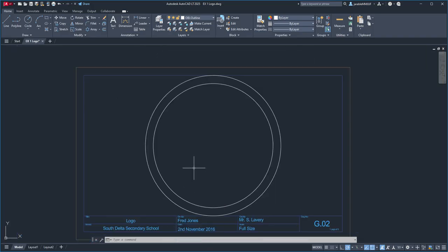Okay. So I'm going to start with my line tool up here. And I'll just start somewhere right about here. Now, you can see that as I move my mouse, I started drawing my line. As I move my mouse, I get this little guideline. That's a vertical guideline. And what it helps me do is draw lines straight up and down. I also can get a guideline for drawing horizontally.